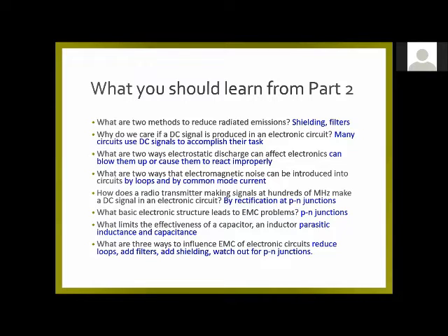I did have one more example of how we fix that circuit with the LED. If you put inductance on the transistor base through a bead or something, that will make it much better. And that's done a lot for discrete components. But there's nothing you can do here if it's in an IC, unless you can put something on the input line. Maybe a bead on the input line might help.